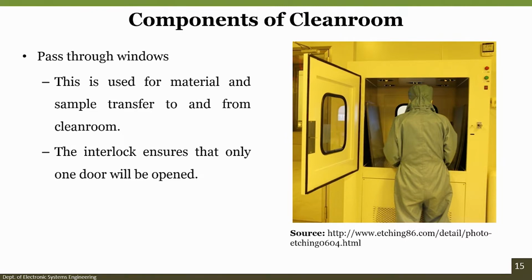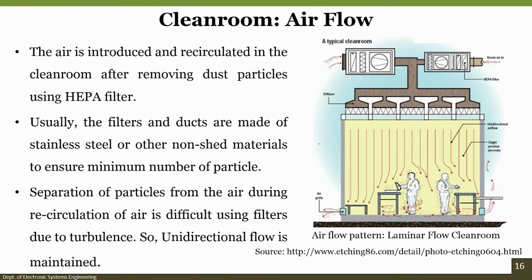So if you wear all these gowns, the whole clean room hood, and you don't want to go inside, you can open the pass box, put your item, close this door, let the person inside open the other door, and that person can retrieve the material. So it ensures that only one door will be open at one time, and thus the passing of the material is possible.